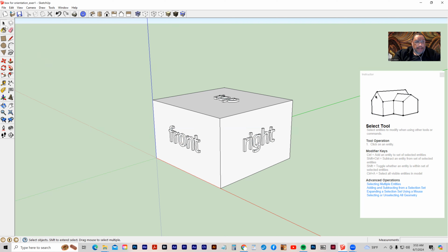Now, when you're working in SketchUp, everything is oriented around edges and faces. So with my direct selection tool, my standard selection tool, I can select any one of these faces, or I can click and select an edge, right? I can click and select an edge or a face, right? And I can hold down the Shift key and select a number of edges. And then if I click again on the same edge, it will deselect it.